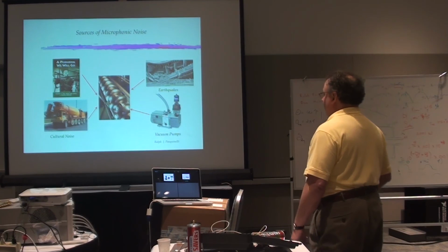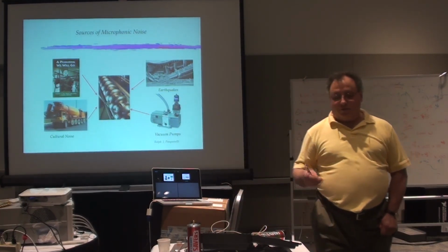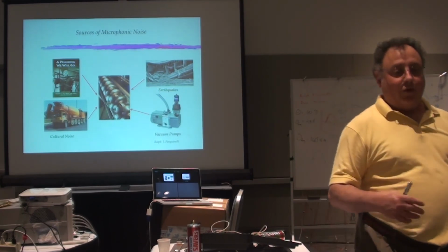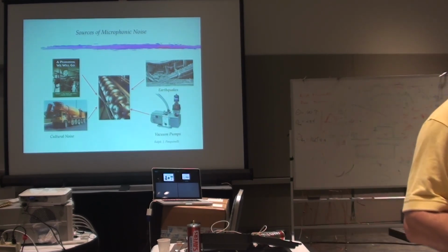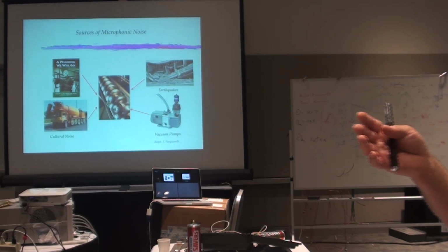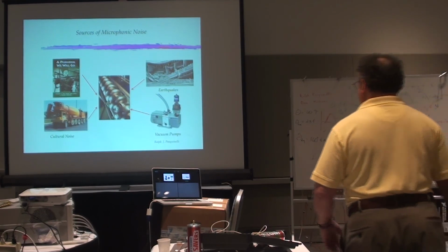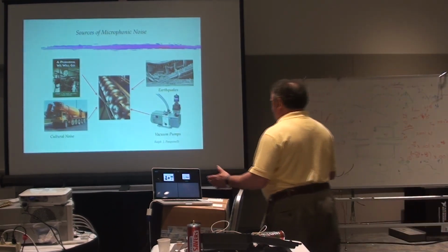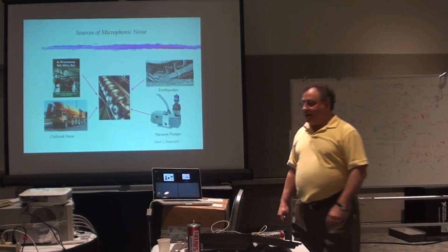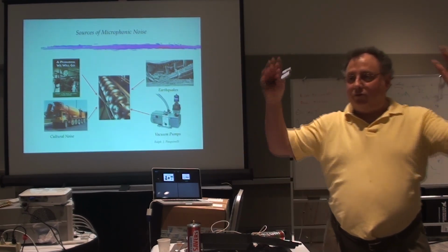You know, old Curly over here, plumbing. I'm not sure about your laboratory, but we have noisy plumbing. If there's any air whatsoever inside the plumbing... what do you want to do with plumbing? You want turbulent flow. If you get laminar flow inside your cooling systems, you're not going to be taking heat away from whatever's getting hot on you. So you need turbulent flow. What's turbulent flow? Noise. And if that noise happens to be near that cavity, it's going to shake the cavity. And when it shakes the cavity, it's going to put all kinds of sidebands on there. And those modes may be absolutely horrible to the beam, and you've got to get rid of it.